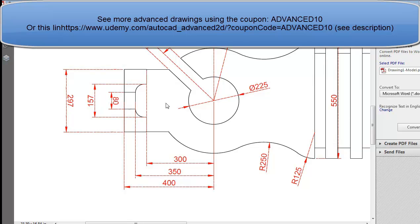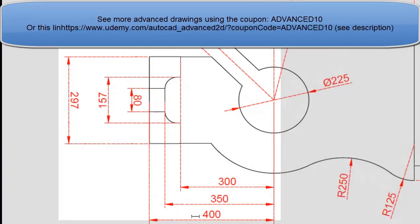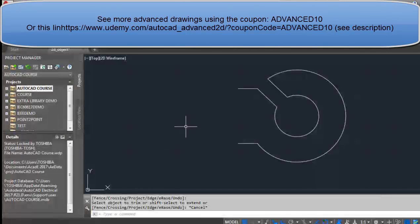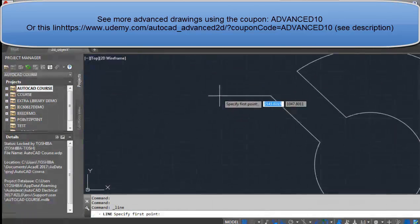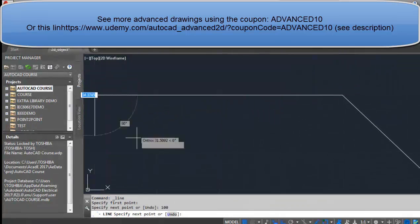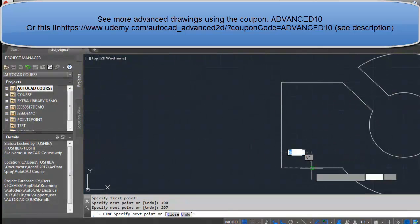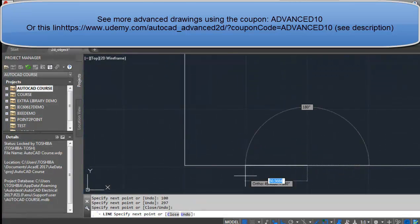So let's continue to the left of this drawing, and as we see we have another line, okay, from this point to this point, and have a distance of 400 minus 300, so the distance is 100 again. So let's go, and again from this point 100, go down for 297, and connect those 2 points that we have them here. Okay, now we have this shape.